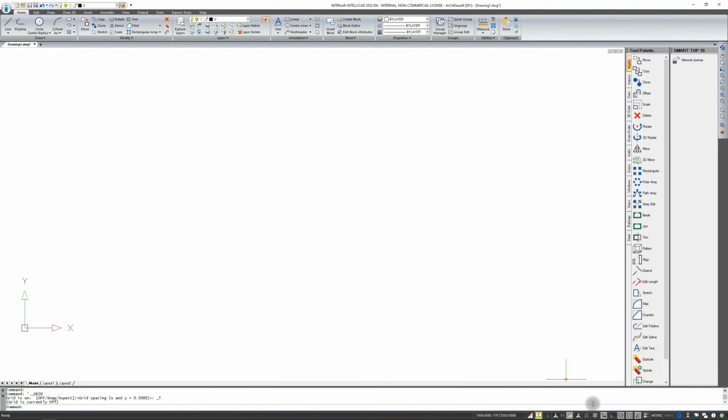The first thing you have probably noticed about the program is the grid. Ta-da! The grid can help you draw because it can be your modular mesh. If the grid snap is turned on at the bottom of the status bar, then the cursor will stick to this grid, and this grid will be an auxiliary element for drawing.